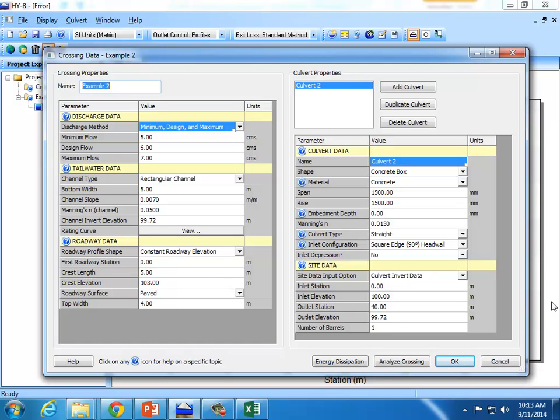For example, the given information in the problem doesn't tell you these elevations, so I just said, by definition, I'm going to have this be 100, and then everything else, like the roadway elevation and the outlet elevation, comes from this decision.